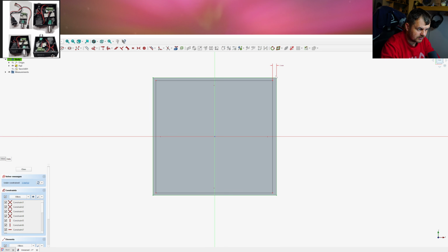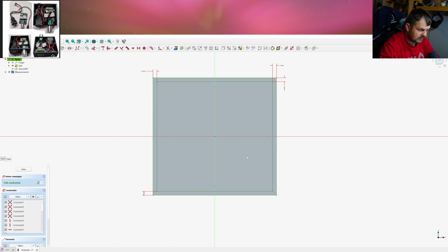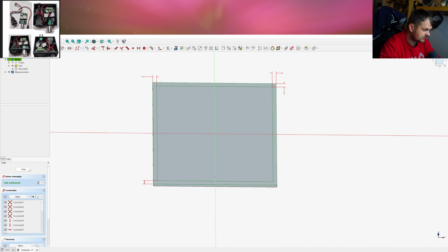And as you can see, it's 2 millimeters. And we want this corner and this corner to be 2 millimeters in vertical. So it's I, 2 millimeters, enter. And now this is 2 millimeters. We want the same from this one, length 2 millimeters, and this one in vertical, 2 millimeters. And now we will have 2 millimeter wide or thick walls. So we're closing this sketch,